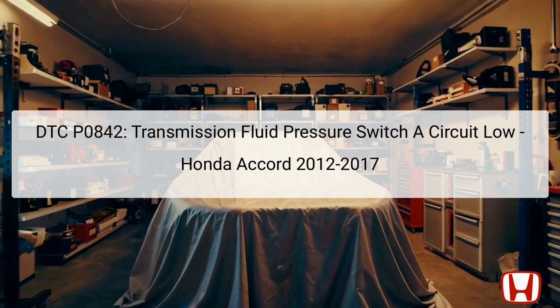Welcome to this troubleshooting guide for DTC P0842, which refers to a low circuit issue with the transmission fluid pressure switch A, specifically for the second clutch in the Honda Accord from the years 2012 to 2017. This diagnostic trouble code, DTC, indicates that there is an electrical circuit problem affecting the operation of the transmission, rather than a mechanical failure within it.